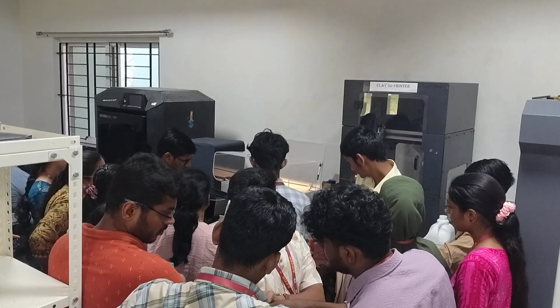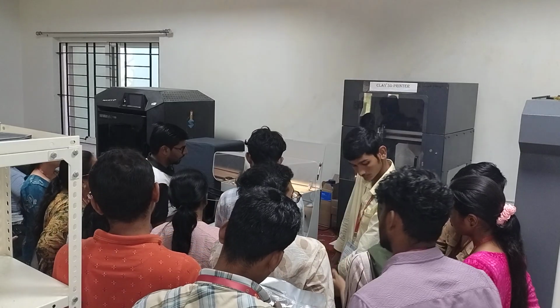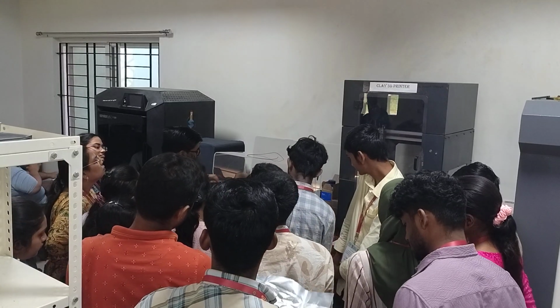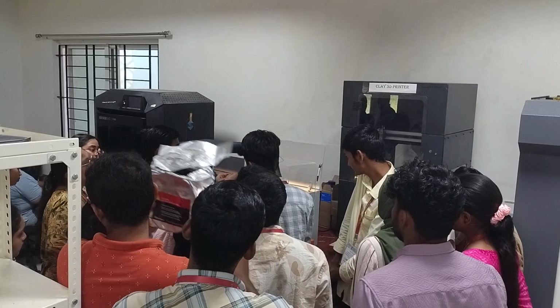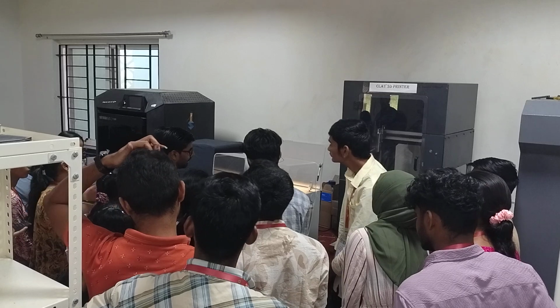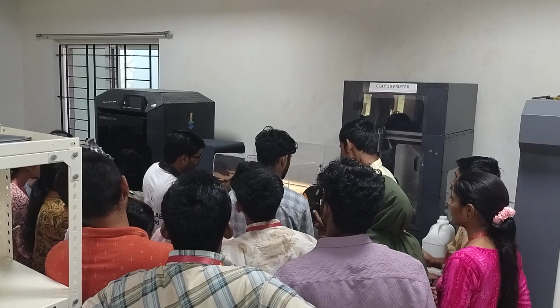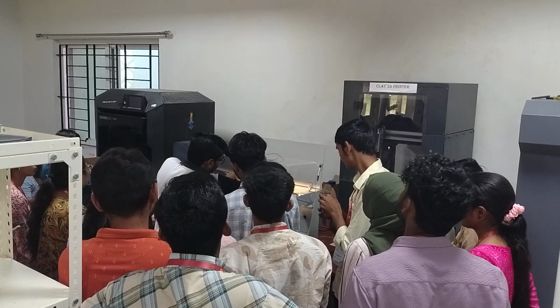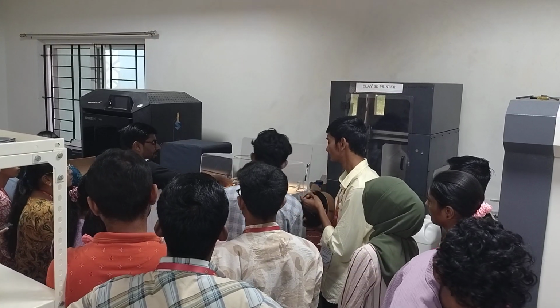Since I have removed this bottom tube, I place it back and then insert it. Sometimes what happens is this fiber also comes and gets stuck here, and because of that, this filament gets stuck there and you have to remove all these parts. So I prefer some extrusion and then placing it back and then tightening.